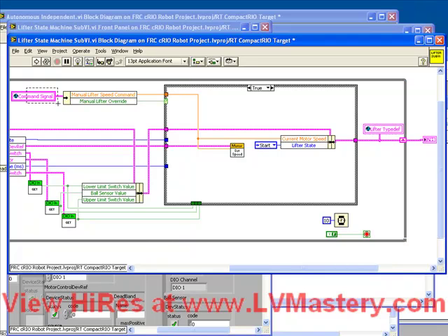And then we discussed the concept of the command signal global, which sends commands from the TeleOp VI to any of the other sub-VIs, and pointing out that you must make sure that the global doesn't get written by multiple places, but it can get read by multiple places. And finally, we talked about how we can use this approach to make sure that our autonomous code and our TeleOp code don't have to have separate sub-VIs and separate behavior.